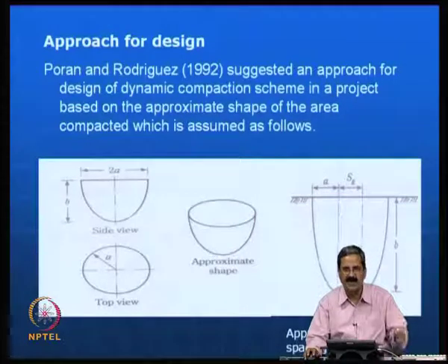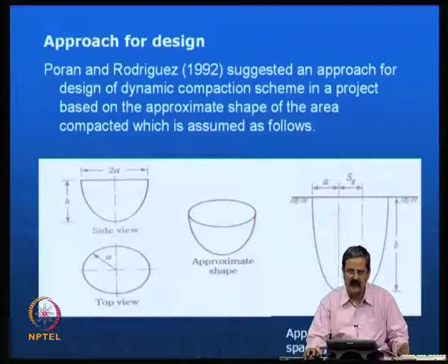You must be able to have the initial soil profile, using either a CPT profile or an SPT profile, and also after compaction you must be able to get the SPT profile or a CPT profile. We will see how they are useful to us in a minute, but the first important thing is how you go about design.